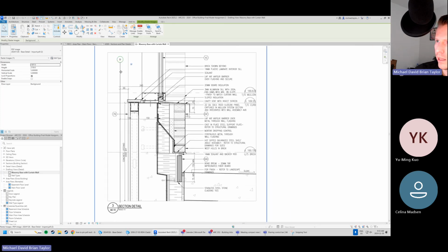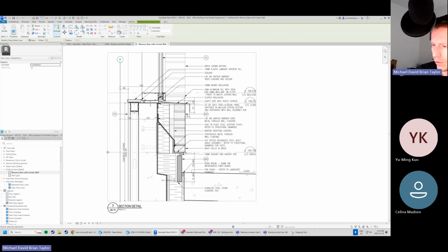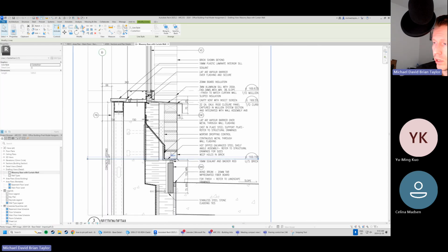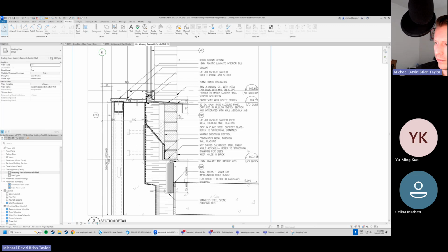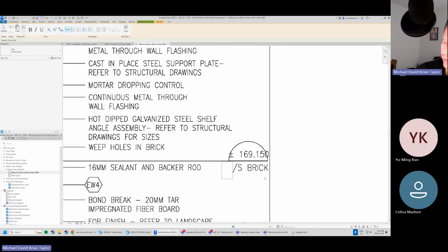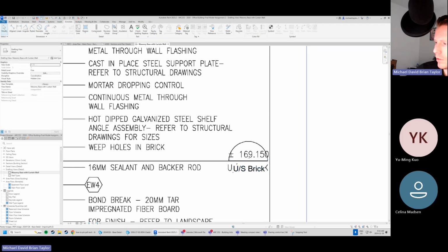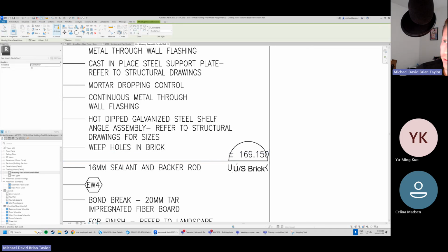Okay, so we got our grid in there. Let's draw. I like to use the create similar command here, so I'm just going to type CS, give us a little level. Again, this is very different from how we were using Revit previously. So please be mindful that you are just drawing 2D components right now, like you would draw in AutoCAD. It is by no means the best way to do this. It is a way to do it if you've got an existing set of details, to get some information into the drawing. So that shortcut there is TX that I keep typing. So TX and CS for our little drawings here. CS is command create similar.